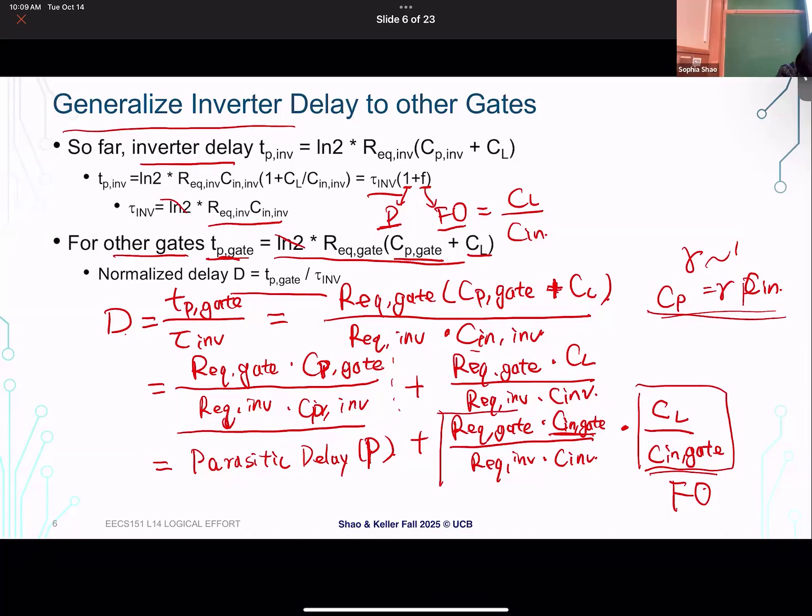And this, we'll talk a little bit more. This is basically what we call logical effort. The effort to drive the logic function that is independent of the sizing, independent of the load, that's just the intrinsic property of the topology, right? So that's why it's logical, right? It's all about the logical expression, and just by the fact that we're having more inputs that lead to a different stress compared to the inverter case. And this is what people call logical effort.